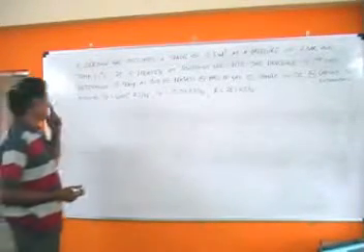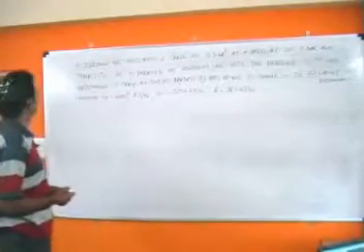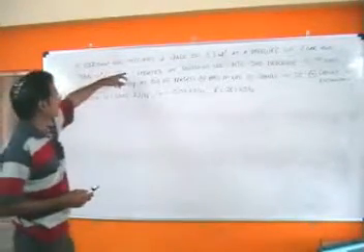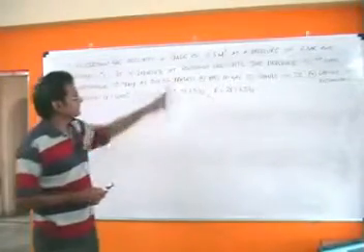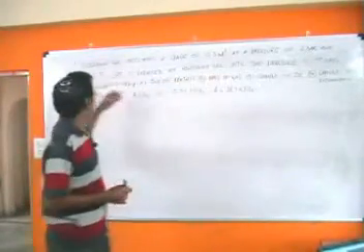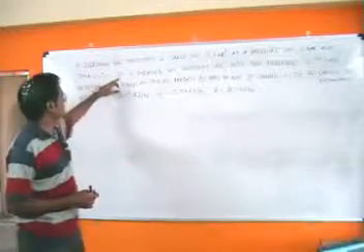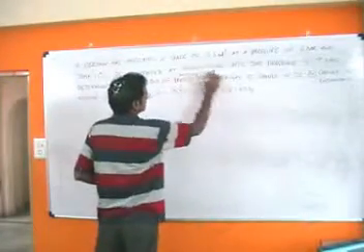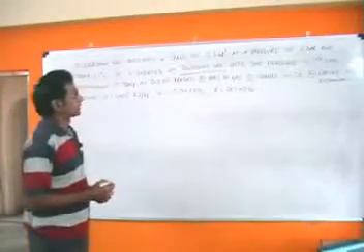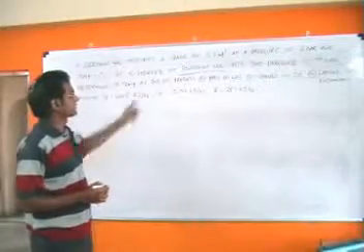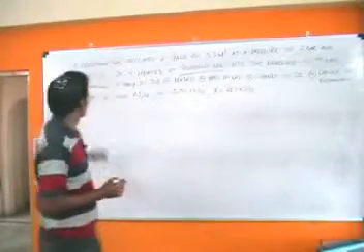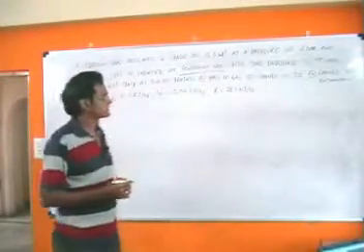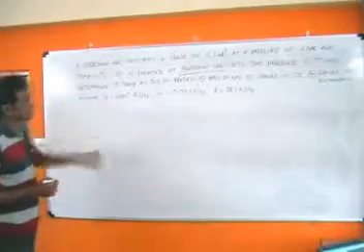Now we will take up some problems on these thermodynamic processes. Let us take a problem on a constant volume process. The problem says a certain gas occupies a space of 0.3 meter cube at a pressure of 2 bar and a temperature of 77 degrees centigrade. It is heated at constant volume. So this is what is important: you need to understand the process under which it is expanding or getting compressed. At constant volume until the pressure is 7 bar. Determine the temperature at the end of the process, the mass of the gas, the change in heat energy, and the change in enthalpy.